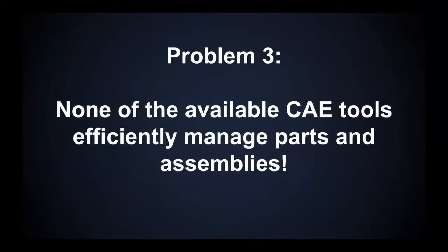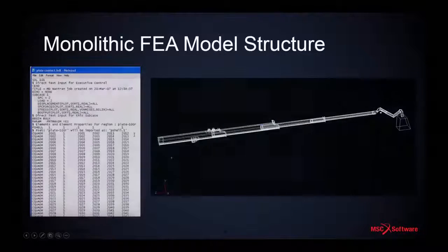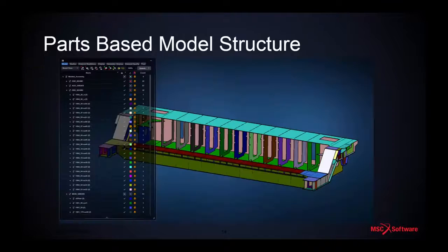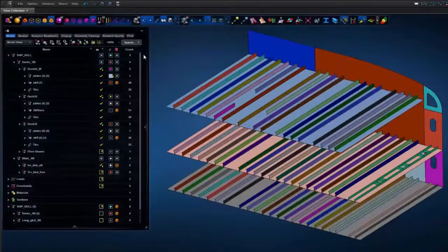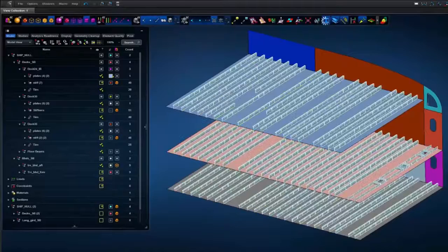Traditionally, CAE systems are parts and assembly agnostic for a good reason. The FE solvers that they rely on flatten the assembly structures into one monolithic model before processing the data. Unfortunately, superstructures typically have deep product structures and are much better suited for incremental validation of parts and subassemblies before simulating the entire assembly.